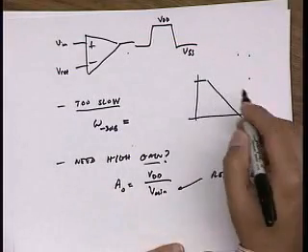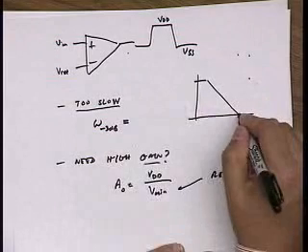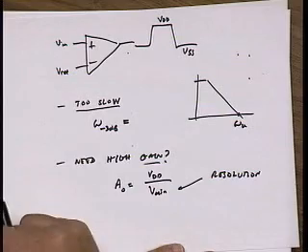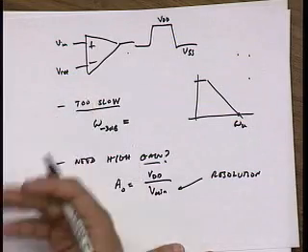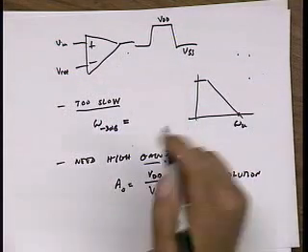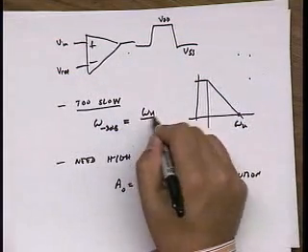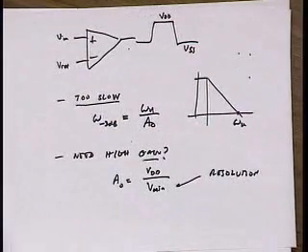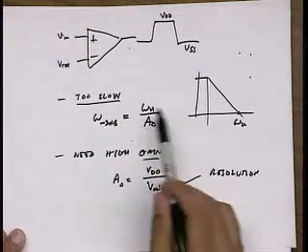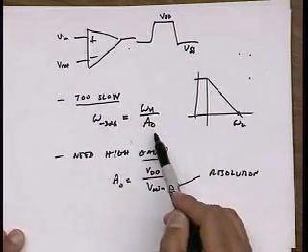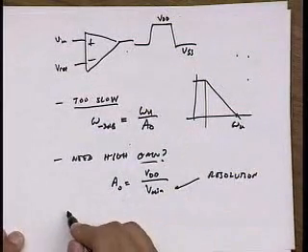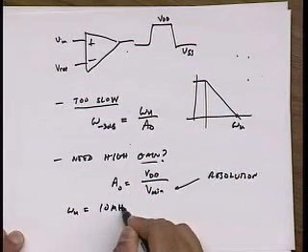Well, I know that if I design an op-amp and I have a certain omega u, right? That's just basically the gm of the stage divided by either the load capacitance, or if I have an output stage, which I do here, by the compensation capacitance, right? So the 3 dB frequency is omega u over A naught. And if I have an application where I need lots of resolution, then this could be a very low frequency, right? How low? Well, let's take an example. Let's say my omega u is 10 megahertz.